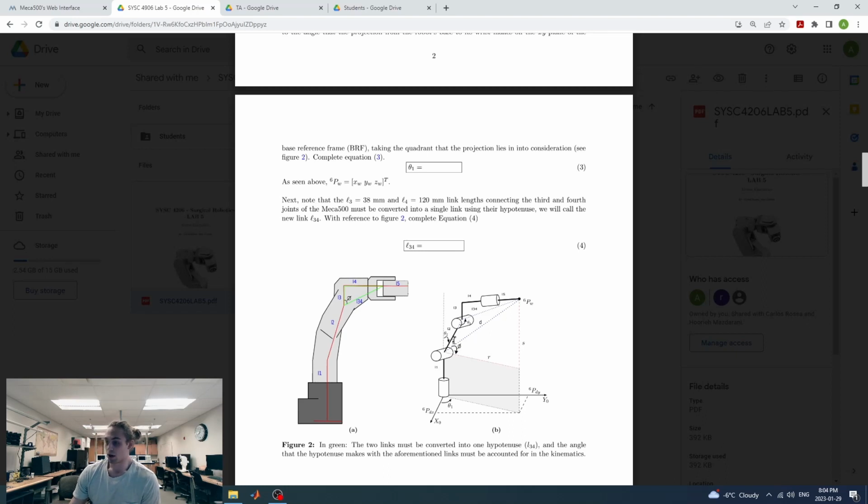So we know that between this bottom angle of the blue triangle and this bottom angle of the red triangle, the sum of those two things minus pi by 2, I guess flip the sign, will be the angle for theta 2 here. So we know that the sum of all of these angles has to equal 90. Yeah, and then we can also use cosine law on this blue triangle plus or minus the constant to determine the joint angle for the third joint.